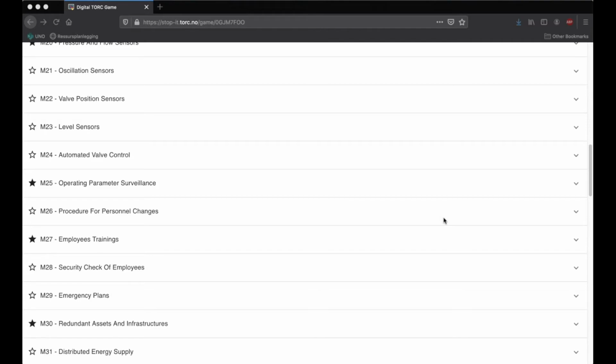one direction. Yes, but if the distribution network is connected with another distribution network with more pressure, these automatic valves can open and control the pressure that you supply to the sector that is cut by the leak.